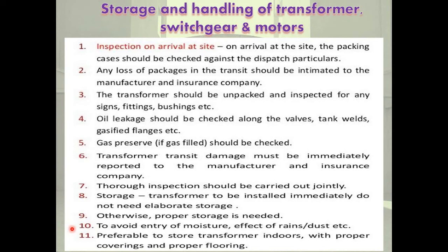Direct sunlight, rainwater, dust, gases, water and smoke should not be present in the storeroom. Chemicals, batteries, gas cylinders and explosives should not be kept in the same storeroom. There should be proper pest control; no rats, vermin, or other troublesome pests or rodents should be allowed in the storeroom. Machines should not be kept on a mud floor. The floor of the store should not be subjected to vibrations. In case of vibrations, the machines should be placed on rubber blocks. There should be a no smoking sign in the storeroom.